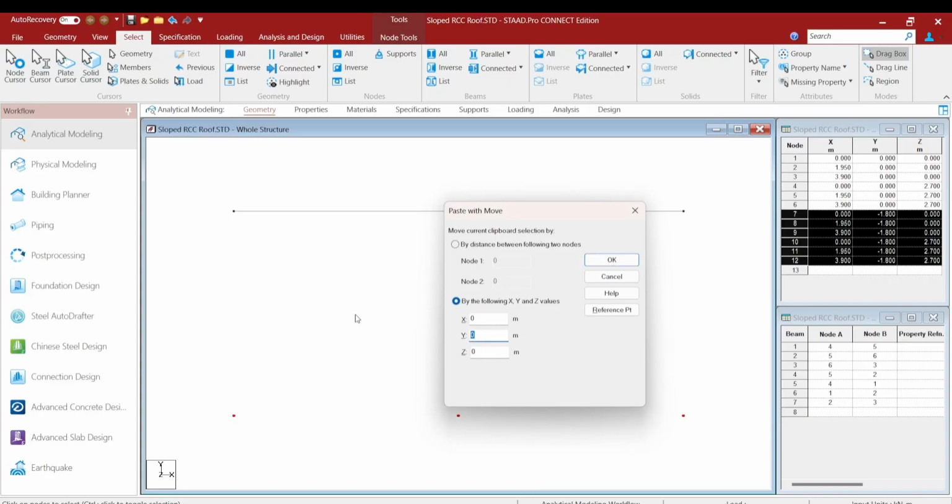Let's go 0 point. So we'll have a positive direction. So the minimum would be 0.5, 0.7. For the amount which we'll select, we should remember that there will be a brickwork between the tie beam and the plinth beam. So 0.7 will go.